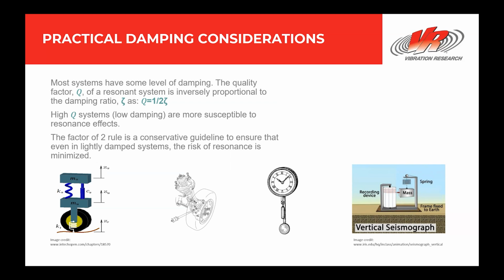So an underdamped, when zeta is less than 1, you can think of car suspension systems. So when a car hits a bump, the suspension system, which is composed of springs and dampers, allows the car to oscillate a few times before coming to rest. This provides a balance between comfort, which is less oscillation, and quick stabilization.